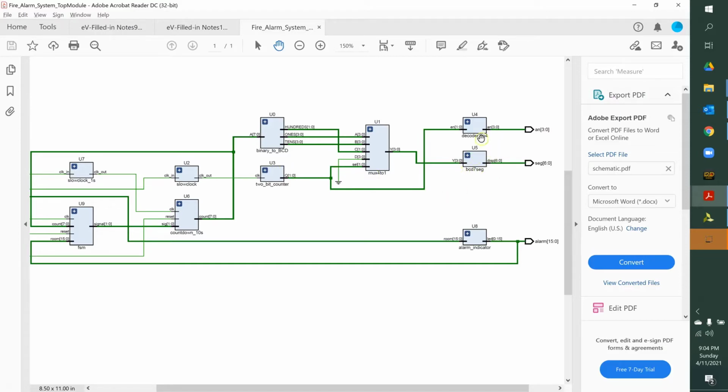Okay, so this decoder makes sure that one of the segments is lit up and the other ones are off, and it just keeps on refreshing the 7-segment display at a refresh rate of, I believe, around 25 milliseconds. Now we are only using 2 of those, but it just keeps refreshing all 4 7-segment displays.